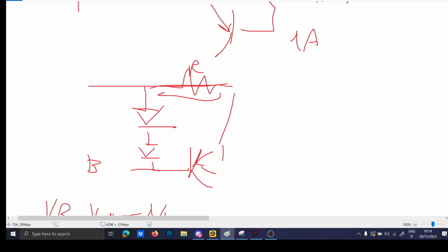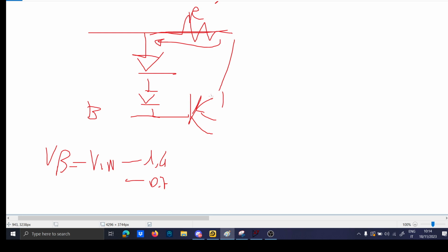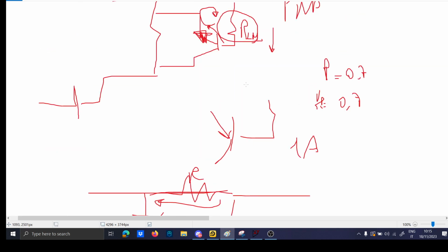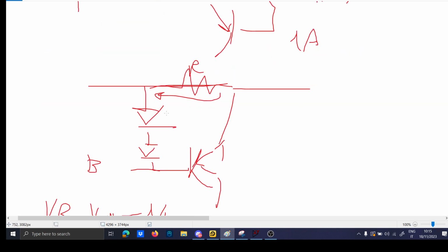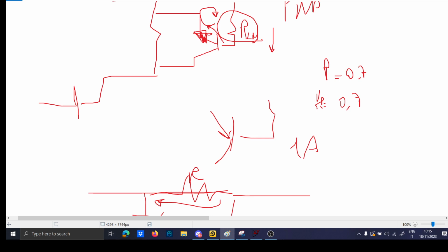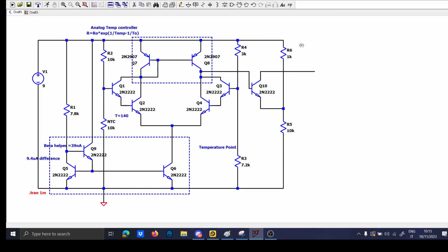When the drop of this resistor reaches a certain threshold, which is given by these 2 diodes, the current protection will be triggered, and you'll be fine. So there are a lot of circuits like this, really a lot, and they are so beautiful, in my opinion.